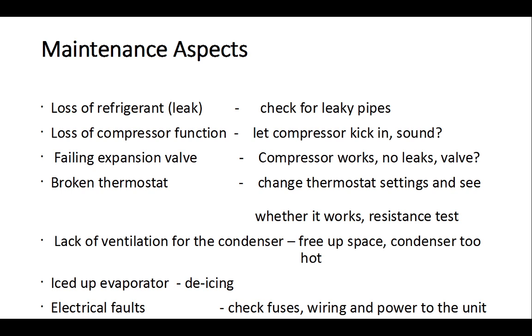Right, failing expansion valve. Compressor works, no leaks. Could possibly be the valve, but they are unlikely to break down really. The thermostat could be wrong. So if it over-freezes or doesn't freeze at all, it could just be that the thermostatic control has gone in the refrigeration unit. So you can do a resistance test to make sure whether they work. Maybe just change them over, manually override the thermostat and see whether you get the fridge to work one way or the other.